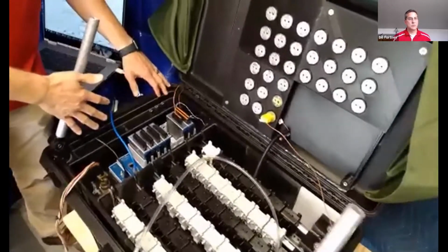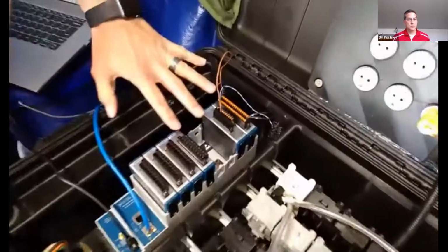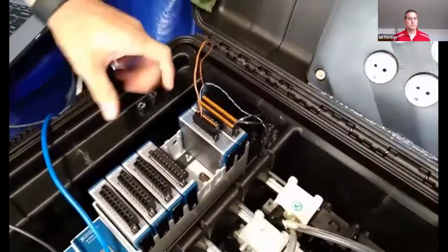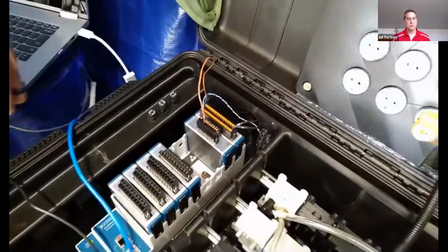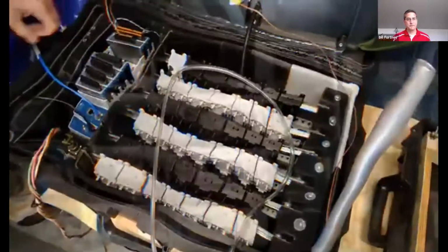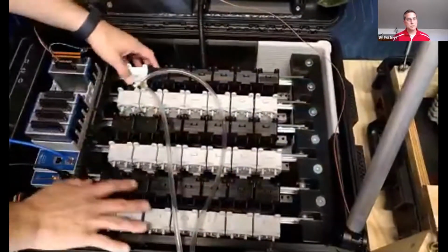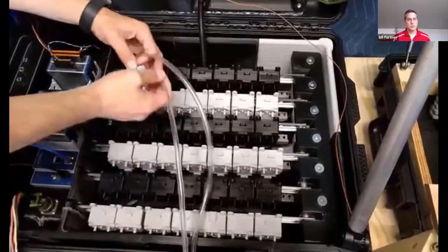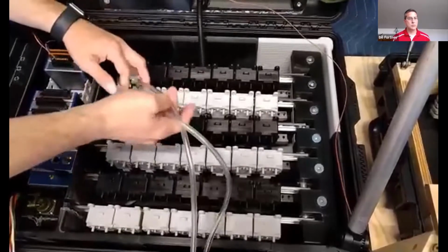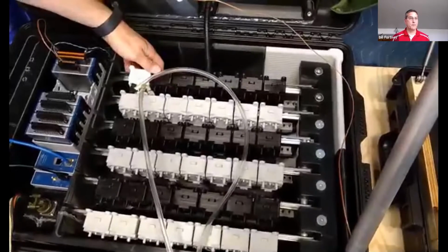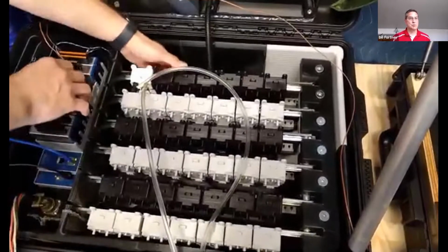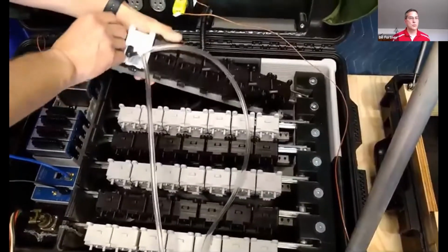Looking at the inside of the case, we have 3 fuses that line up with the 3 modules that are supplied from the power that run the pressure transducers. This is for safety mitigation. All of the pressure transducers are on these DIN rails right here. These hoses go out to the rake and they bring in the data that the rake team is picking up from their sensors. If we look at one of these DIN rails, we'll pull it up.